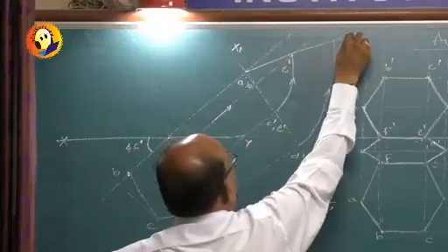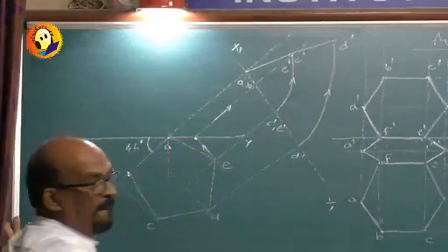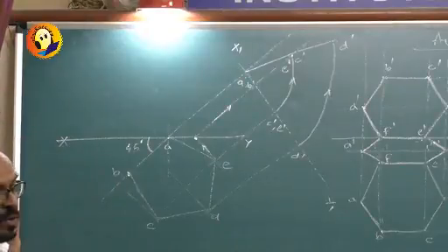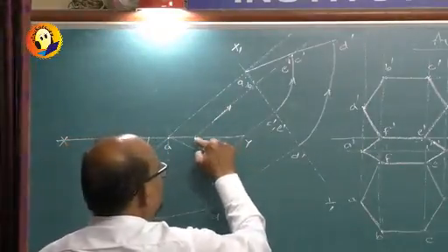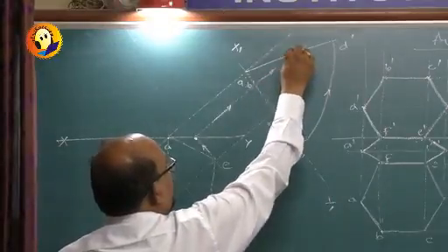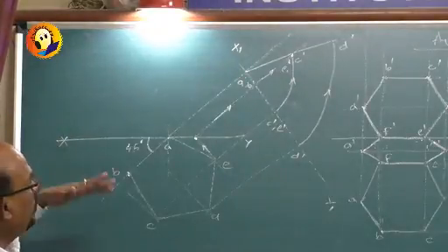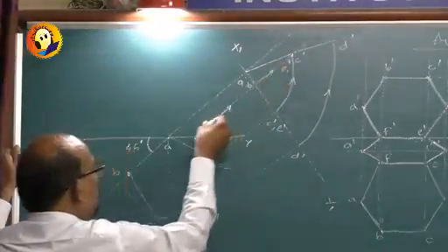To get point D dash. And of course this is going to be C dash. So I have taken this point, extended it, then rotated, I got point E dash, extended it, and onto that I got D dash. Now the procedure remains the same. Take these 2 points down.